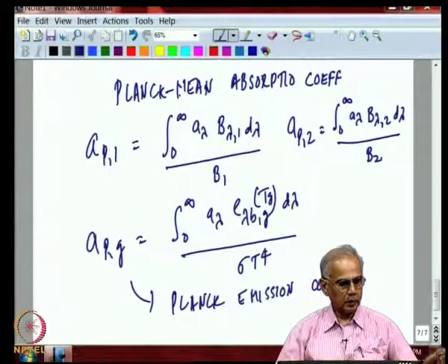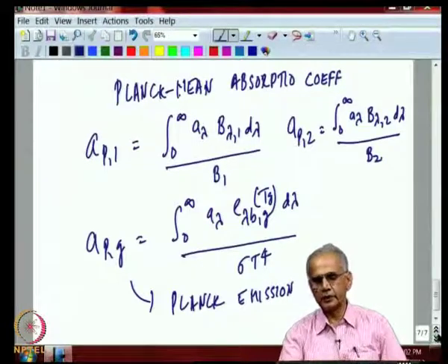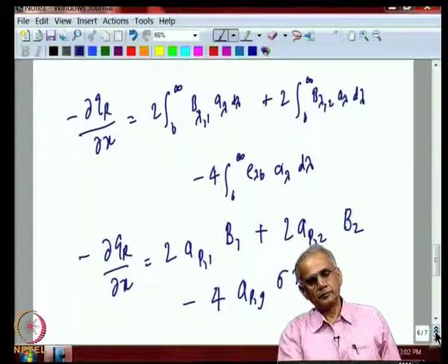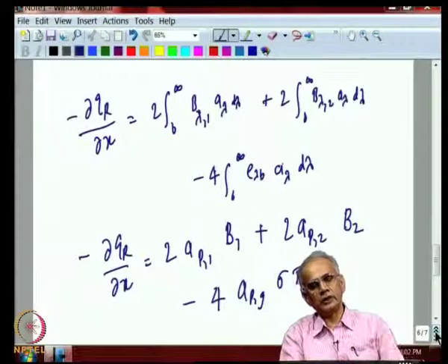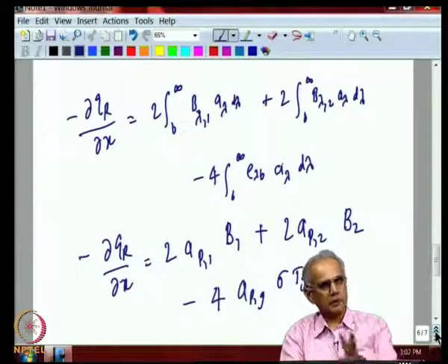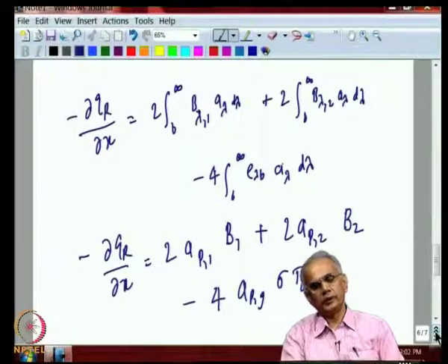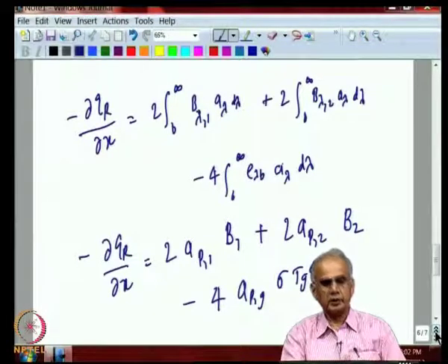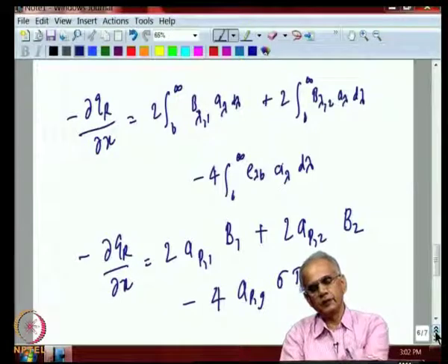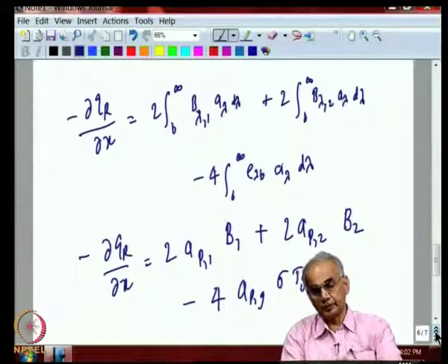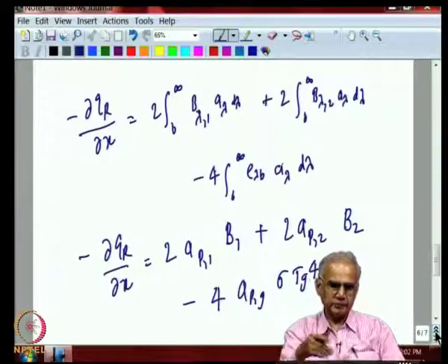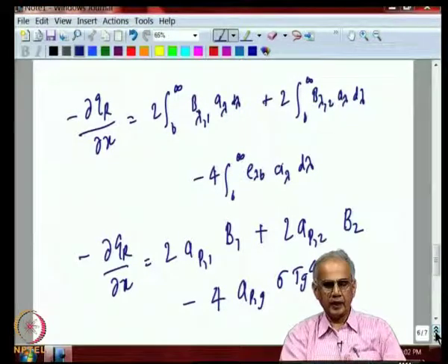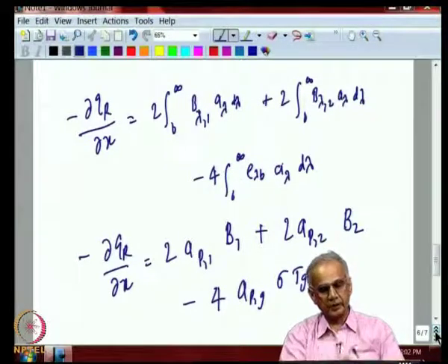So, the thin limit is attractive still for certain applications, because this expression is a differential equation, and this expression can be plugged into the general energy equation, and there will be other terms, and this will be going along with them. So, in some of those cases where people solve these equations, they will be extremely happy that the expression for the divergence of the radiative flux is fairly simple. If you know the temperature, the problem becomes even simpler, but normally temperature is an unknown, it needs to be evaluated. So, it does take some time to get that number done.